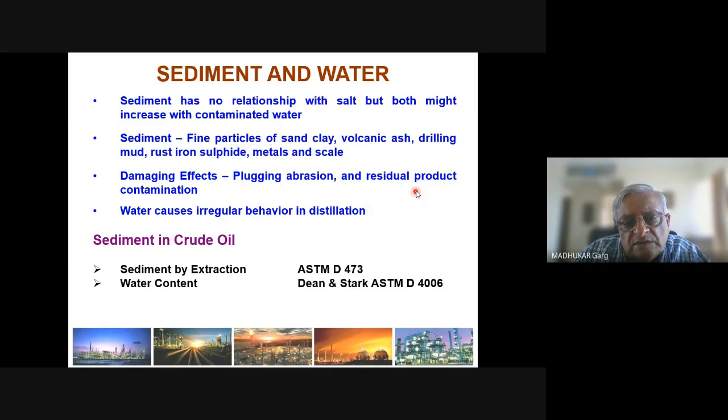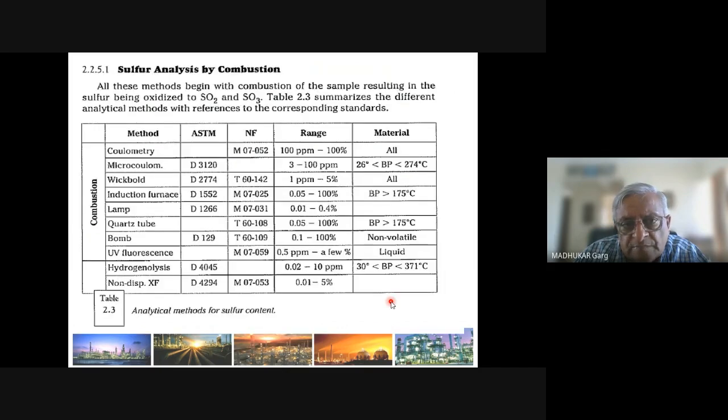The sediments are determined by extraction using ASTM D473. And there's a very popular method called the Dean and Stark method, which is defined by ASTM D4006, by which we determine the water content in the crude oil. And this is free water content.